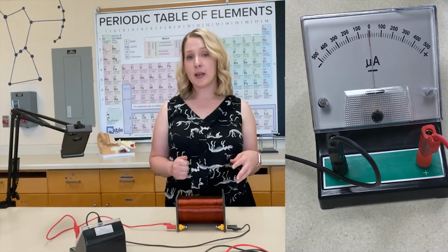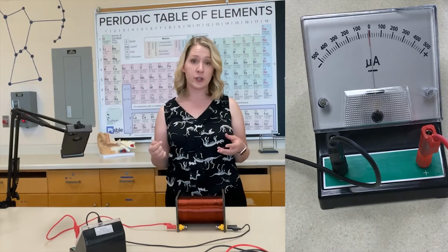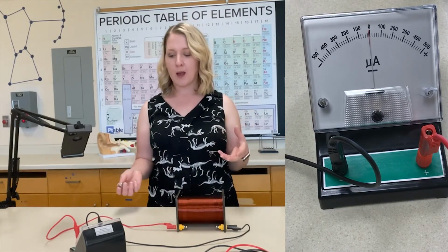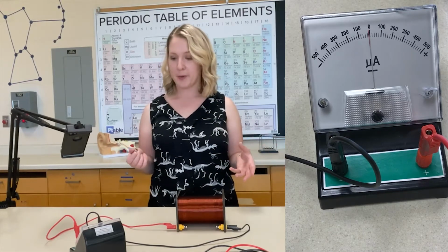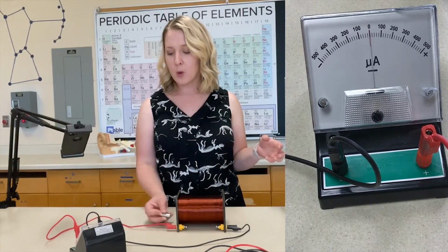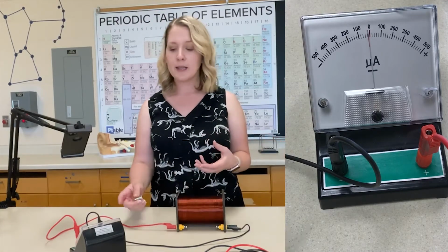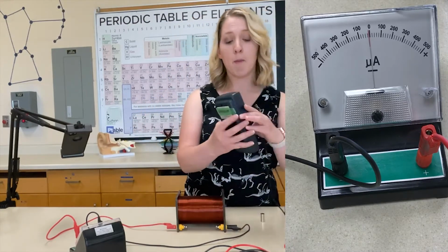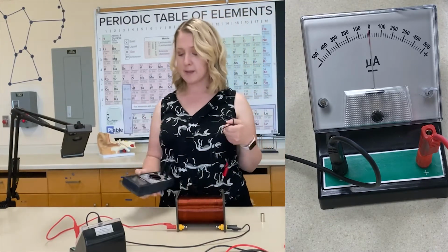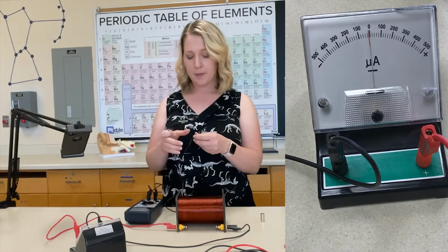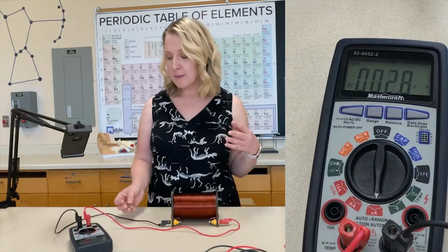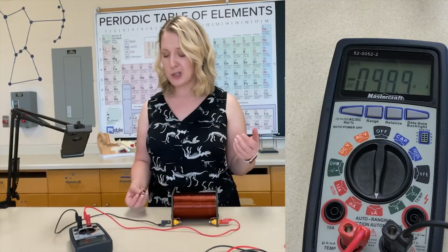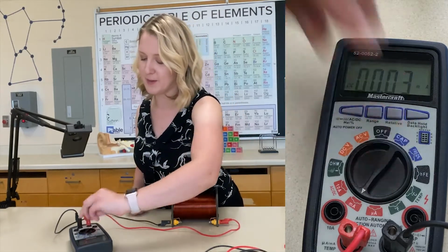We have different factors that your students can change in order to determine how they affect the amount of current generated. Doing this with a galvanometer is not optimal. So it's really difficult if they're going to change some factors to get an accurate measurement on the galvanometer. In years past, I've used a multimeter with a good amount of success, but it's not my favorite, and I'll show you why. Looking at the multimeter, you can generate a current. Once students start to get into larger currents, they may have to change the settings, and they may not know how to do that just yet.